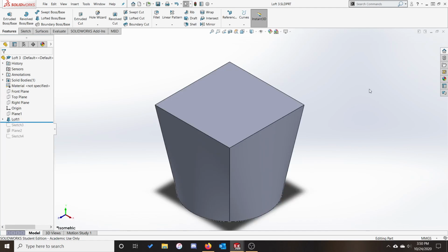Now, onto the dome feature. Dome is fairly simple, as it allows you to inflate almost any surface, and it is often used to add smooth end caps. This isn't always advisable, and I recommend that you consider creating the shape using a revolve first, but sometimes dome is the only option that we have.